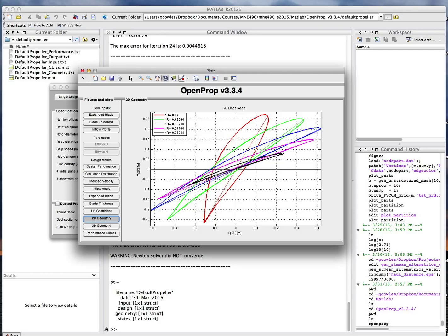I don't think you see quite this drastic a change in things like wind turbines, propellers, because the forces at play are pretty significant, so you have this big thickness variation. You can see it's a cambered profile. It's a slightly cambered profile. Here's the mean. Here's the chord here. So it's cambered. This is the suction side. A little bit of camber to it. The bottom is pretty flat. This is pretty typical of a propeller. The bottom side is fairly flat compared to the suction side, and it's a bit of an odd-looking airfoil.